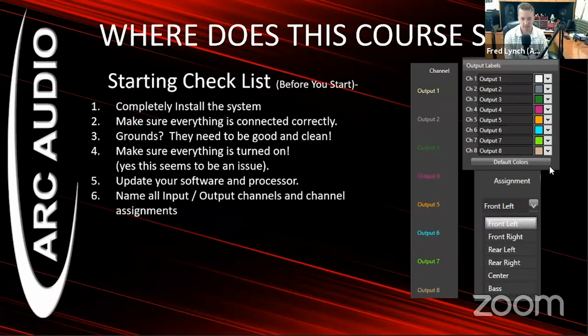You're going to have output labels, and then you're going to have input labels. It's always great to name those because it'll carry on through all the software in the system in the vehicle. And by having those names there, it's a quick reference, and it makes it easier for you to tune, knowing what you're adjusting versus trying to remember what did I have on output 1 or output 2 or output 3.